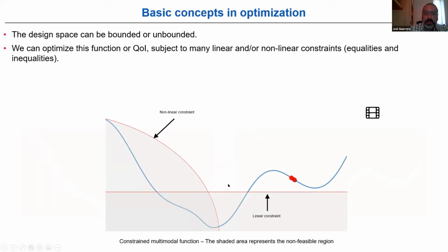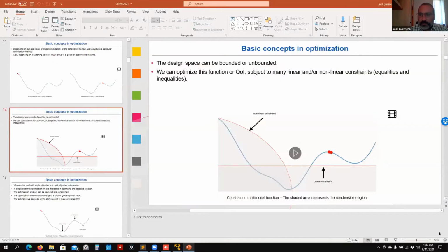And then you can also bound your problem. Here you see that we have these bounds or constraints. We have linear and nonlinear constraints, and then we can force the problem to find this minimum here. This is important because when you formulate your problem, you have to be careful. It can happen that you over-constrain your problem and arrive at a solution that you think is the right solution. So it's up to you. This is very open, but you need to formulate problems. It's not something where you press a button or press enter, launch your simulation and have it. You need to formulate your problem beforehand.